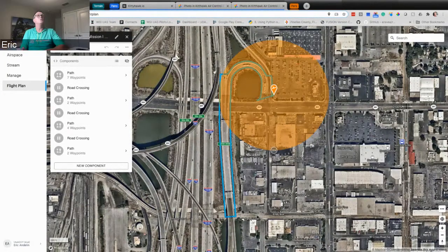Yeah, well, you're going to set drone speed when you're creating your missions, not necessarily during flight. So you're not going to take over. If you do anything with the sticks during flight, you've paused the program. So you're not going to want to do that, but you can make those adjustments when you create the mission. So you may want to have it approach at full speed, and then have it map at 13 miles an hour. You can make those adjustments when you create the mission.